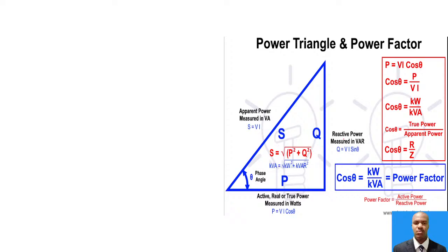Now again, the diagram is simply summarizing the initial discussion. But there are some things I would like to emphasize more here: for a leading current, the power triangle becomes reversed, and this provides a key for power factor improvement.